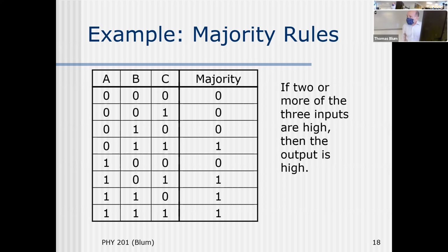Okay. Now, in this approach that we're talking about right now, we look at the outputs. Here are the outputs. I look at the outputs that are 1s, so there are 4 of them. And I'm going to write that AND expression for each of these outputs that are 1s. So here's this first one. A is 0, B is 1, C is 1.